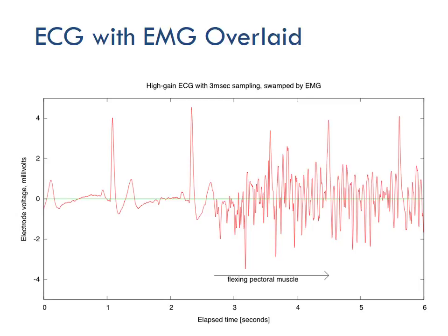But then around 3 seconds, all of a sudden you get noise, so much noise. And you're thinking, well, if I was measuring right before and now all of a sudden I get all this noise, where is that coming from? And it's actually coming from muscle. Like I said previously, muscle is a really great amplifier. Your heart is a giant muscle and it amplifies.